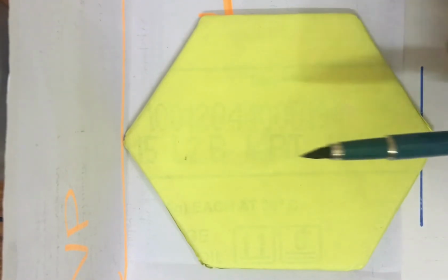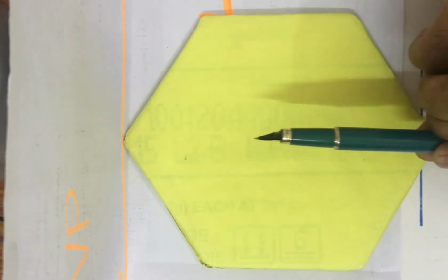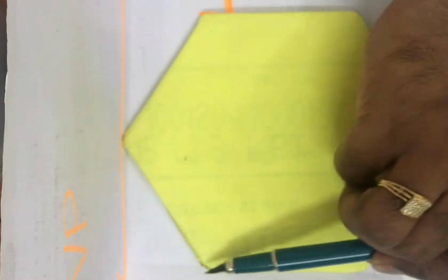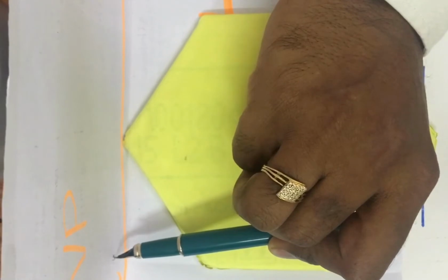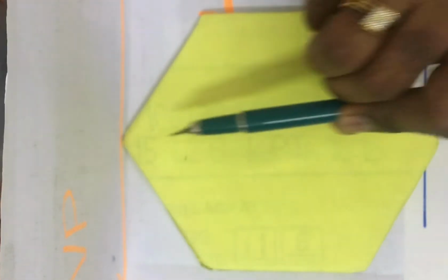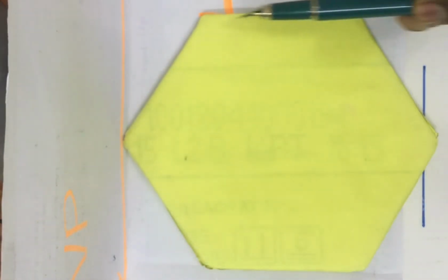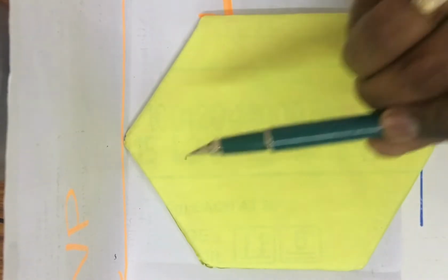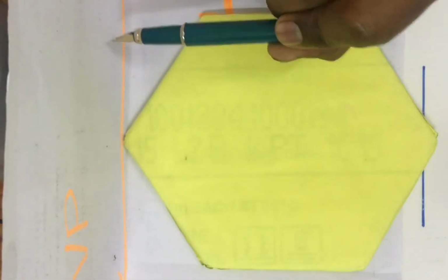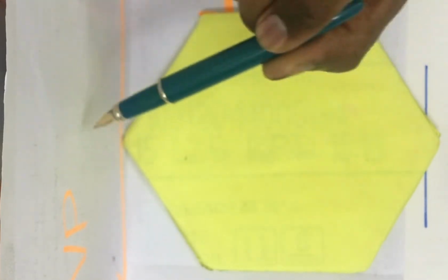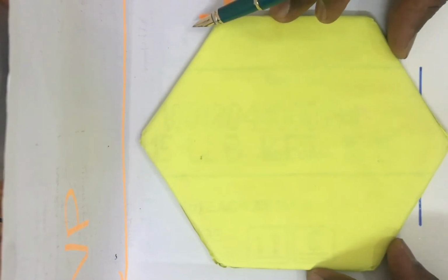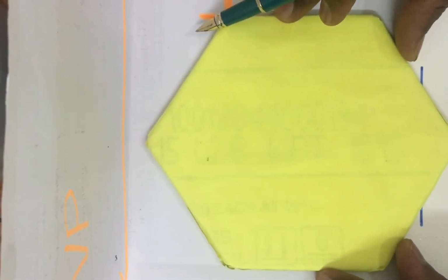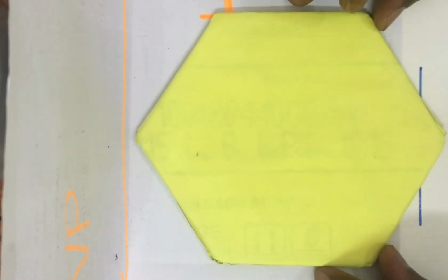Later we are supposed to view from the front. So, when you see from the front, you see a point, and the point keeps reflecting on the vertical plane, and along this you are going to get one more point, and along this we are going to see one more point. So, join all these points. We are going to get a line above the reference line at some distance. They will not be giving any distance above or in front, you are supposed to draw at any distance from the reference plane. So, let us see how to draw this problem.